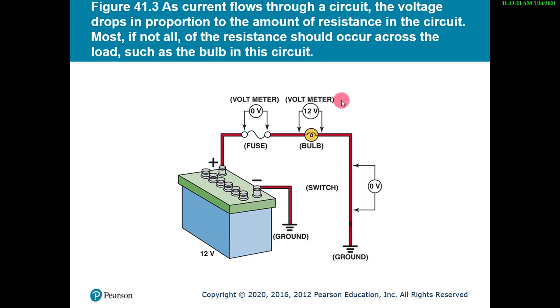And we'll get into things like what's referred to as back probing a connector, where you can slide a needle in to get your measurement, but you never want to pierce the jacket. We're going to talk about that extensively, but on a fuse, you can test either side of a fuse. So when current's flowing through here, your voltage drop should be negligible. Now this says 0. I'm not going to say it's ever going to be true 0. There'll be a tiny amount of voltage drop across the fuse, but we're talking millivolts. Not enough to affect anything.